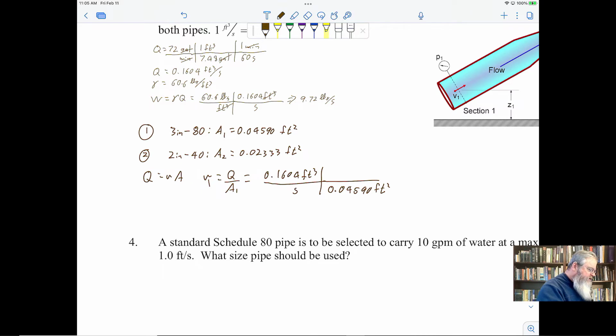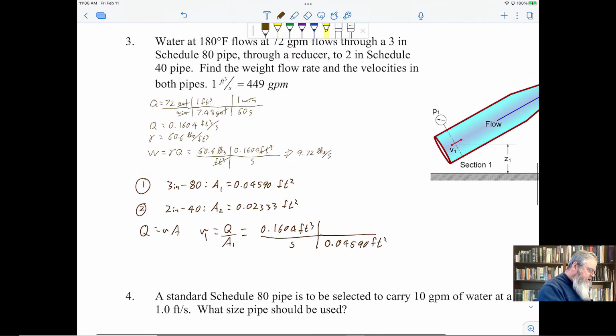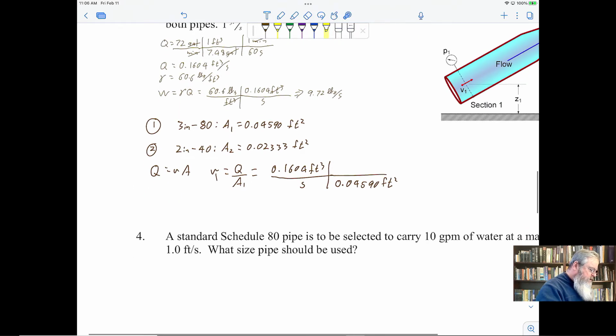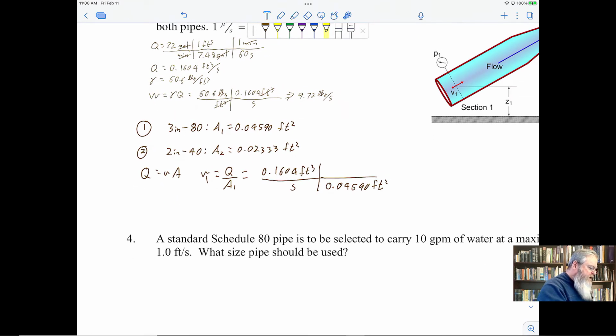Kind of good thing that I did this conversion up here to cubic feet per second. Not inches, but cubic feet. Partly, notice that the inside of the pipe is given in square feet. It seems to be about feet, not inches. Mott's kind of a big fan of feet instead of inches, it seems, and that's fine. So these square feet cancel, and I'm left with feet per second, a perfectly valid unit of velocity.